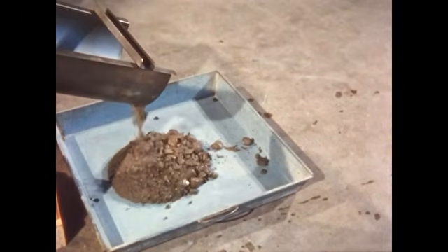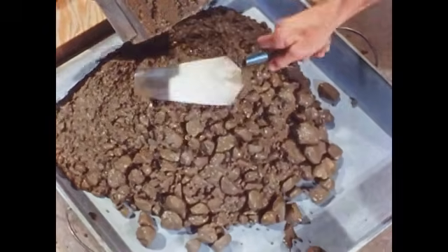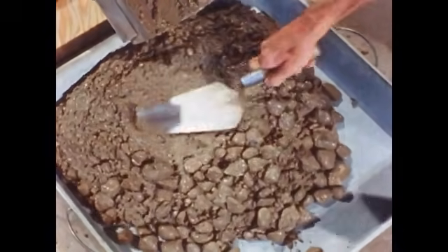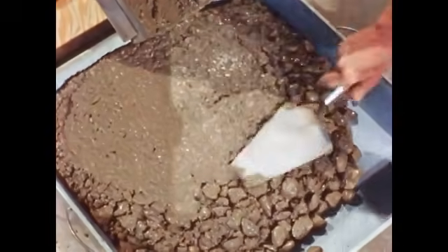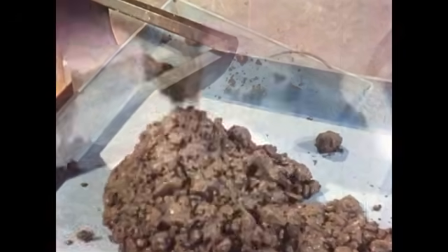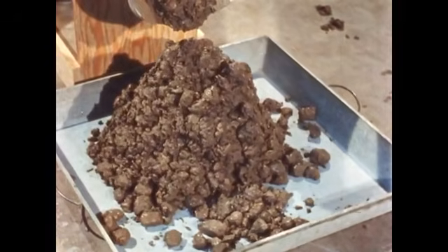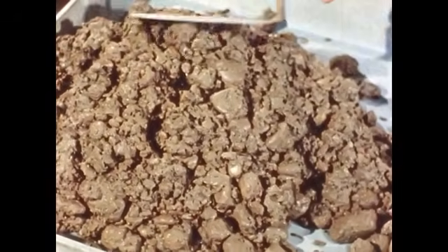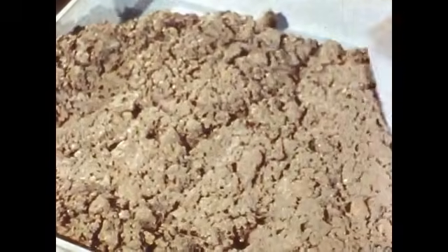This mixture is quite stiff. When deposited, little segregation occurs. There may be some bleeding, but it will be much less than with a sloppy mix. To minimize segregation and bleeding, use the stiffest practical mix of concrete. This is a plastic, workable mixture of concrete with an air entraining agent added. There is no segregation or bleeding, and the mix looks and feels buttery.